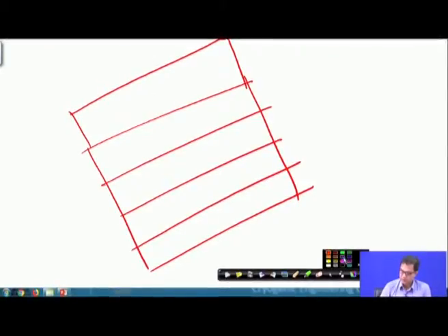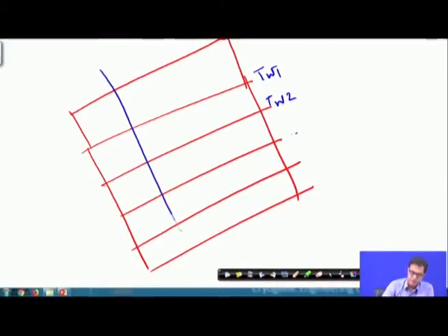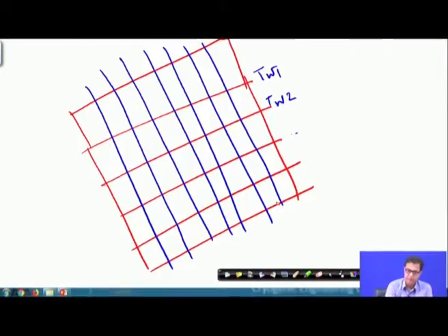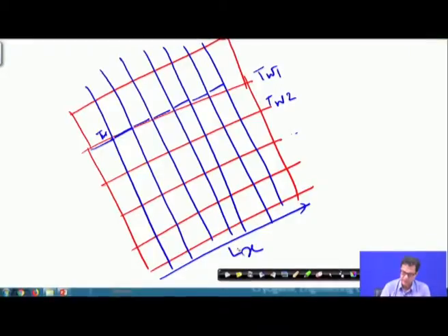So, the separating wall temperatures are Tw1, Tw2, etc. When we divide this entire exchanger into a small number of segments, we can find the intermediate plate temperatures, say Tw1 at this position and at this position, because this is going to vary with the length of the exchanger, say Lx, and we have the other dimension.